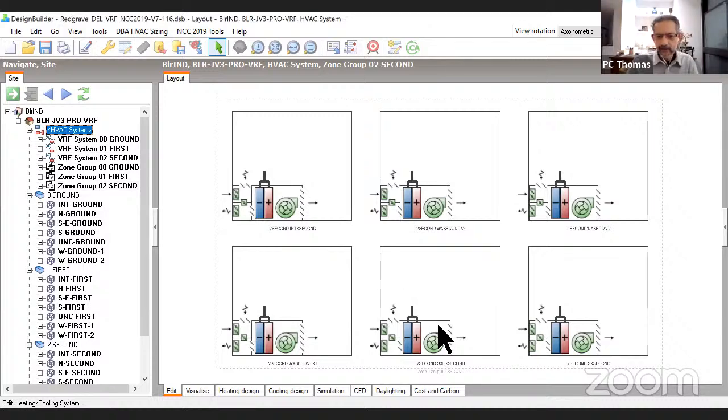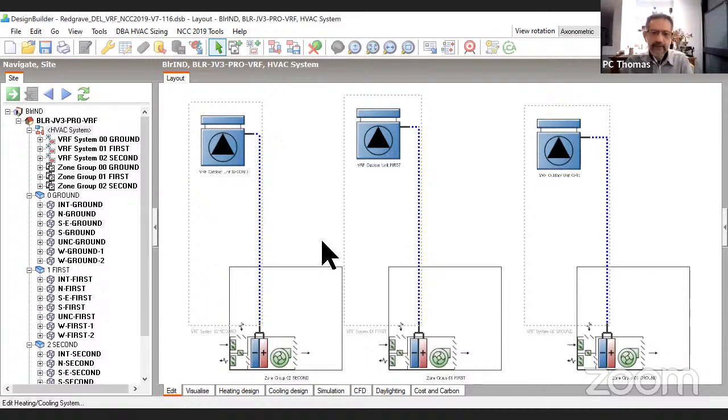So you can do all of that. You can work out the energy simulation. Then it will tell you what is the energy used by the compressors, by these fans, etc. Lighting, any equipment usage you may put in. So all of those things you can work out. Okay. Now you can do very complicated air conditioning systems. So you can do full VAV, 3 chillers, 2 cooling towers, and so on.